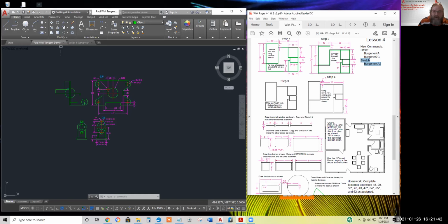We'll add 5 feet along the bottom of the floor plan by grabbing hold of everything that we want to move with a crossing window. The crossing window will turn in this case the vertical lines into rubber bands, and we can stretch the entire floor plan up or down.